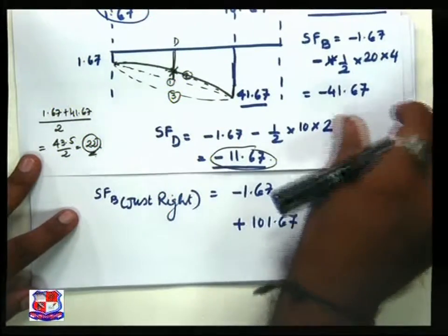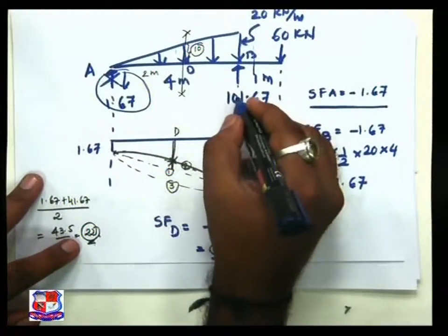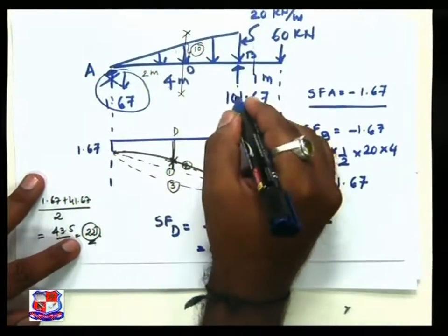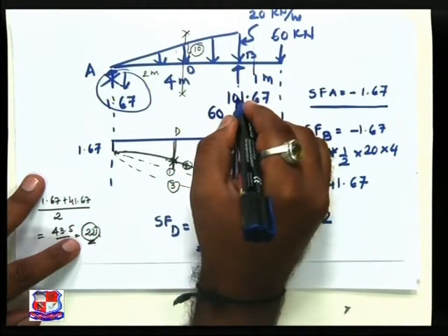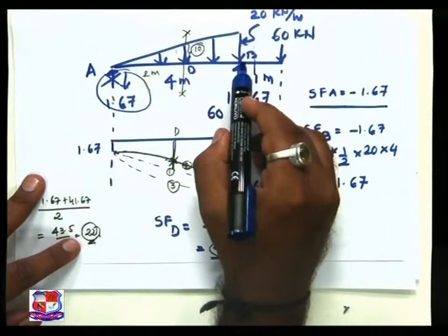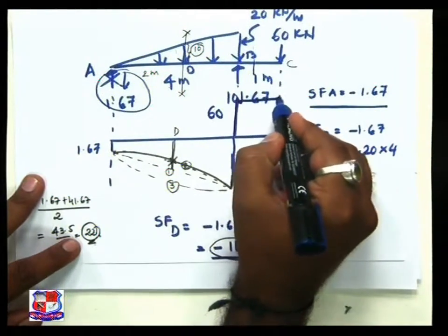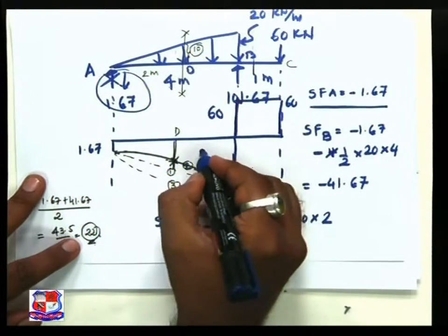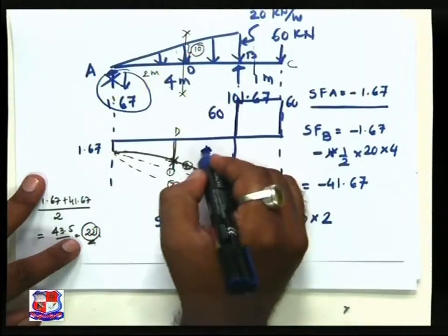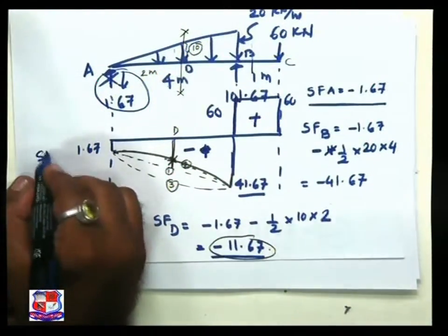So that means at a point load over here, my shear force changes suddenly by 60. After that, between B and C there is no load, so a horizontal straight line, which is obtained directly as 60. Minus sign, this is plus sign. This is my shear force diagram.